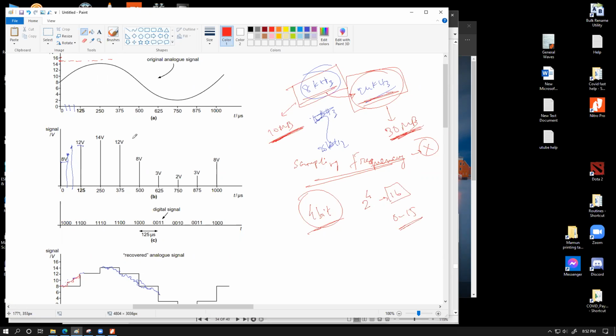which means this analog signal that we're working with, the op amp from which this analog signal was amplified, that op amp should have a supply of plus minus 15 volts, so that the output should not become more than 15 volts, if I can put it that way. Because you can maximum cover up to 15 volts.